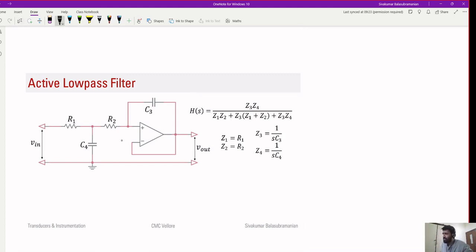So there are different ways in which you can connect your resistors and capacitors to get different types of filters, and these different ways of connecting these elements are called topologies. And I think if I'm not wrong, this is called the Sallen key topology. Okay. This particular circuit here, the way it's connected here, will act like a low pass filter.